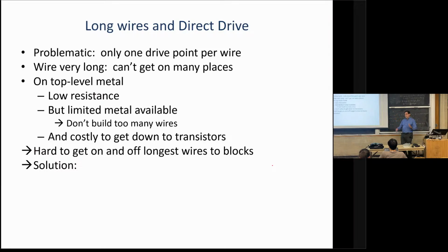And then if I need to connect it up to a bunch of different, maybe it's for a high fan-out net, if I need to connect it up to a bunch of output blocks, I need via stacks all over the place to bring signals down from it to get into the muxes that get me to pins. Which sounds kind of bad, right? So what do you think? What would you do? Segment your routing connectivity patterns so that you have basically a hierarchy. So the short wires will connect to the longer wires, which will connect to the even longer wires perhaps. Yeah. So I'll repeat that for people online. So Isidore said, well, think of routing hierarchy again. Don't connect straight from the blocks, like the output connection block, to these really long wires, because it's going to make them hard to use.